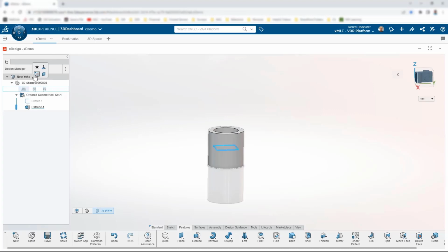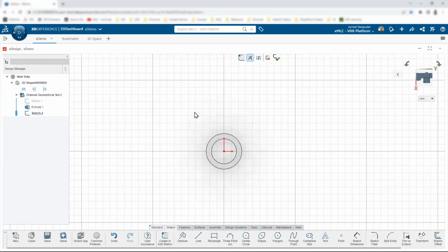Now I'm going to draw up the side portions, the little parts that are going to connect to the monitor stands. To do that, I'll start by drawing a little line here. You can see how when we're drawing it, it brings up the dimension. That allows us to key in a dimension and it'll populate it for us right off the bat. The other thing we can do is click on a line or a sketch entity for that matter, and the dimension will automatically pop up for us.